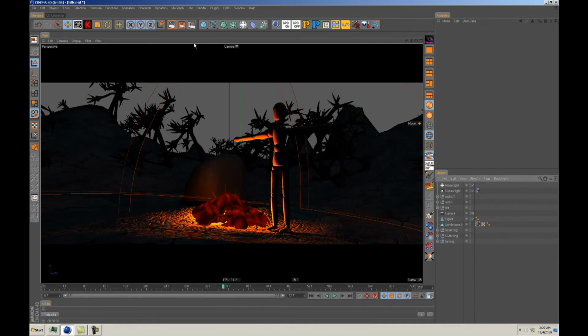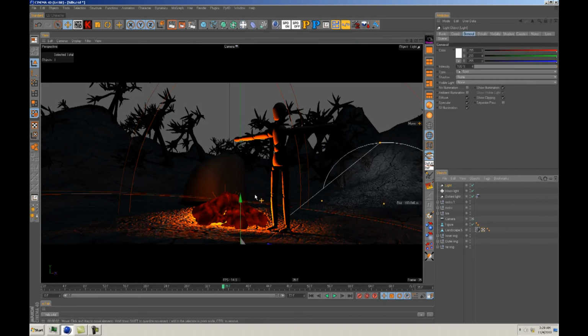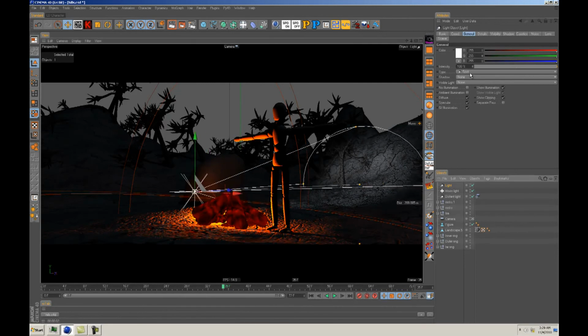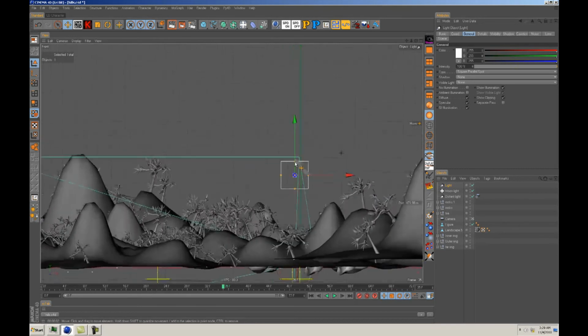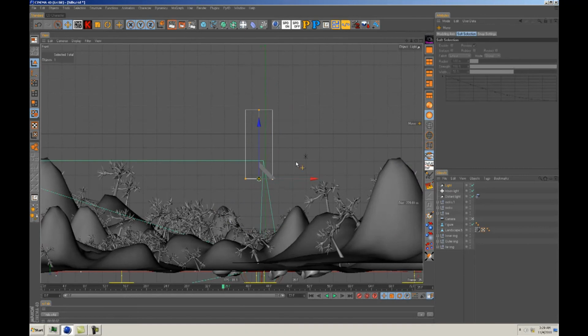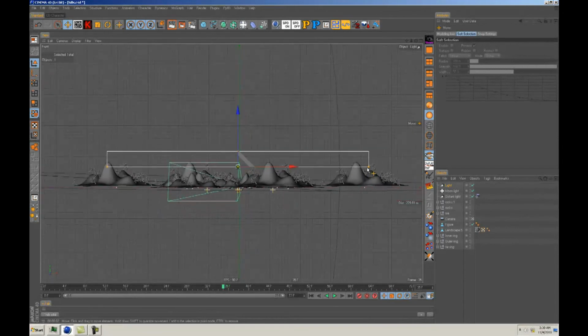And again, this is another hack. If you wanted to do real fog, you'd have to do some kind of liquid system, which Cinema 4D doesn't have built in. I think it's part of liquids. Like in Max and Maya, it's fume effects that does gases and stuff like that. So we're just going to make some fake stuff with a square parallel spot. It's this weird square spotlight. Let's point it up and then make it really big, to cover our whole scene.